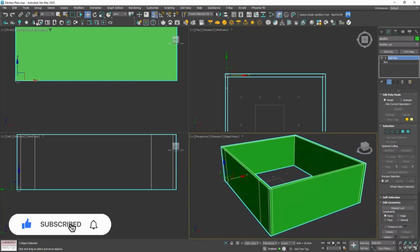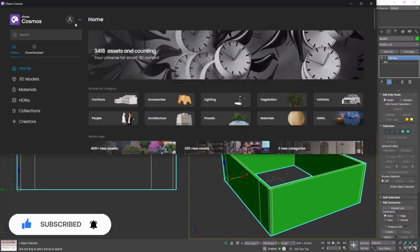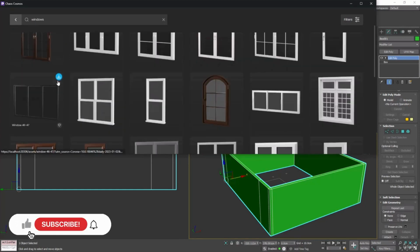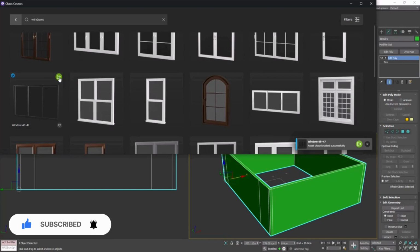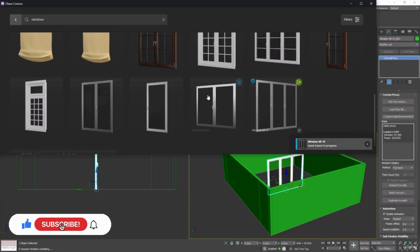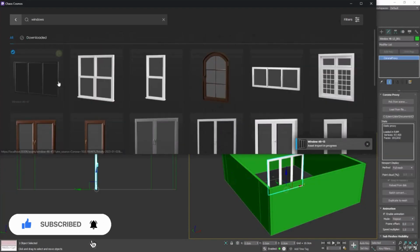CAS Cosmos is an asset library that is available since Corona 8. And in here we have thousands of 3D assets that we can use. So in the search, I'm going to just search for windows. And we're going to use these windows. So we can just click this blue button to download the asset. And I'm also going to download these for our doors. And then the green button means we can import them.